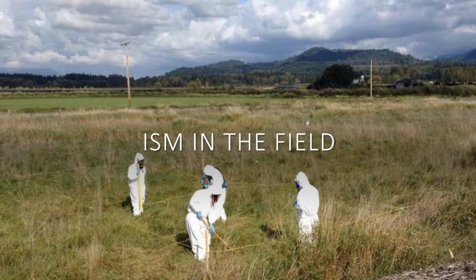This picture shows a second DU at the same site as the previous slide. You can see that the sample grid is laid out with ropes in the foreground. Higher grass in this area made it much harder to lay out that grid and to place the survey markers for each increment location. However, it was helpful in this case to have everything laid out clearly before sampling, because the sampling team were in PPE, which limited the team's vision and movement. The team is sampling soil contaminated with asbestos that required the use of respirators and other protective equipment. So having the grid laid out and the sample locations really helped the team to know where they needed to go next to collect each of the increments to build the samples.